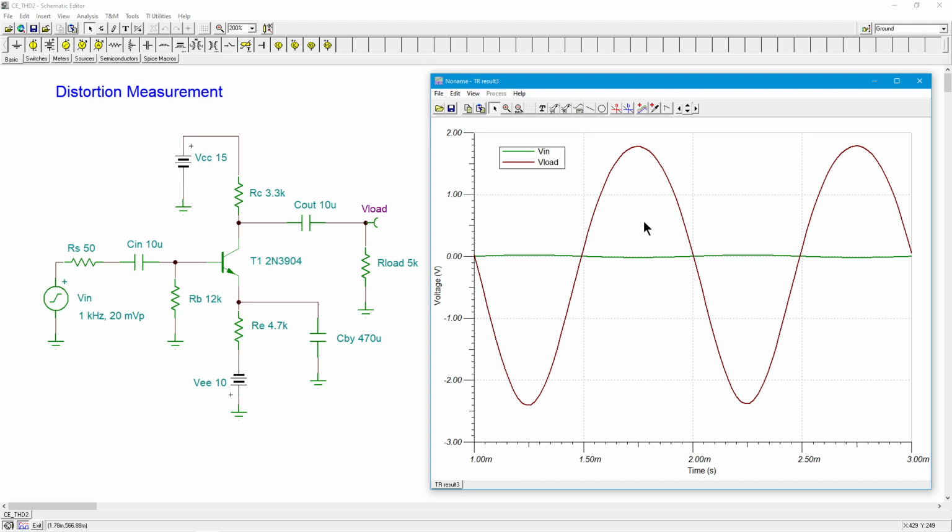Nowadays, we have mathematical techniques. The waveform is actually digitized internally, in TINA-TI here, and then we do a mathematical decomposition on it, a Fourier analysis, to find out what these pieces are. So TINA-TI has this built in for you, but it doesn't just do THD. It does more than simple THD. So how do you get it? I want to know how bad this is.